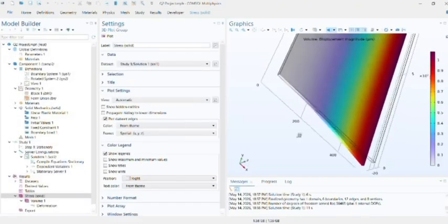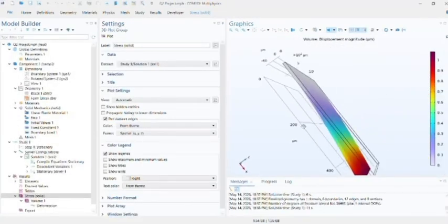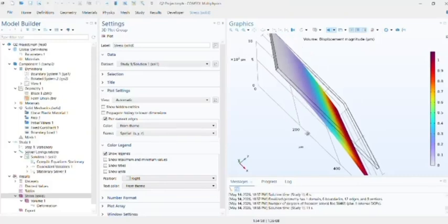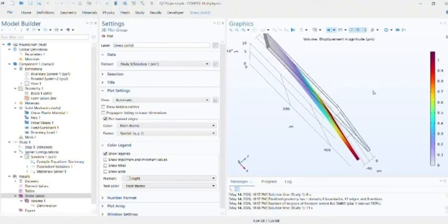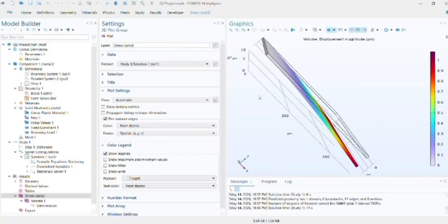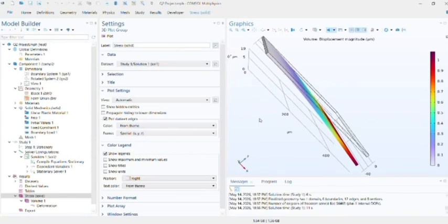Upon computing this result, the maximum deflection drops slightly. This demonstrates that the massive width restricts lateral deformation, known as the Poisson effect, which creates a plane strain condition and artificially increases the beam stiffness.